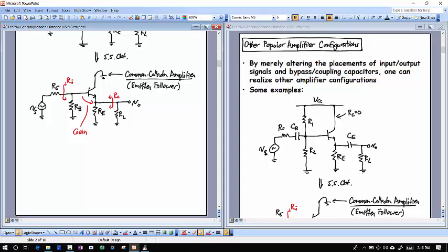Question up there. So on some of your circuits, we had our standard amplifier thing. You have the CE, so it'll be in parallel with RE, yeah. Right, sometimes it'll be parallel with RE, or it'll be serial with VO. What's the difference? Like, do you do one versus the other for specific situations? Yes, you just want a different amplifier.